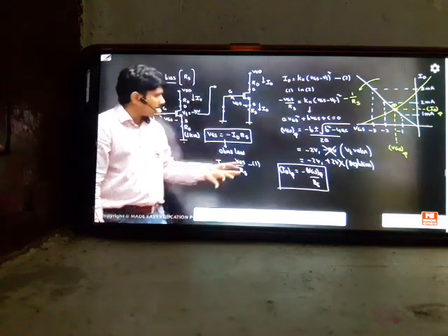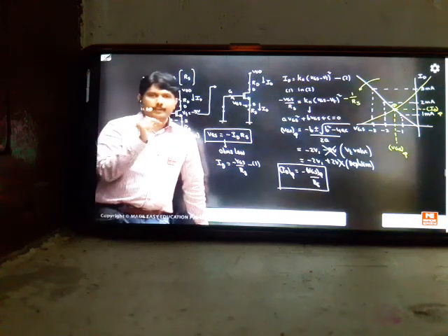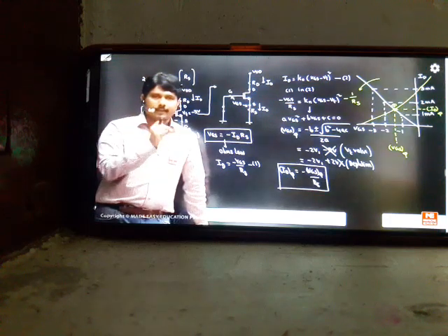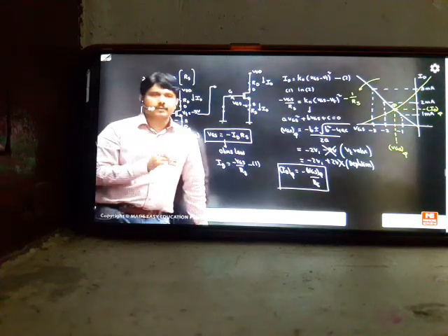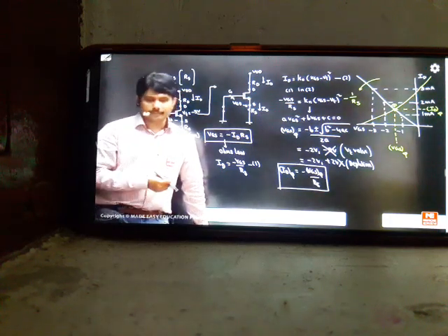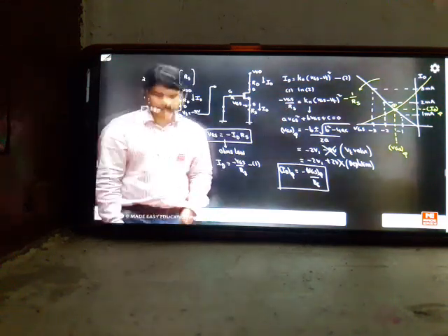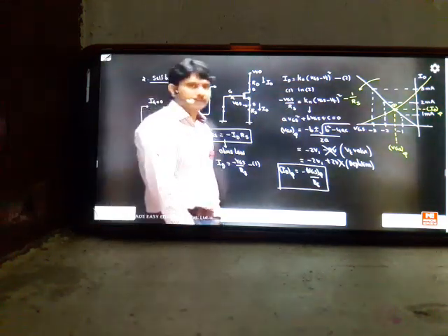Yes, Partha. In these concepts we are fixing the operating point not in the triode or ohmic region, but in current saturation, because current saturation is called the active region in MOSFETs. Like the BJT class, active region. Here in current saturation we have to bias the transistors. That's why we bias these circuits in current saturation. That is the reason we take only the current saturation equation in the class for study purposes.